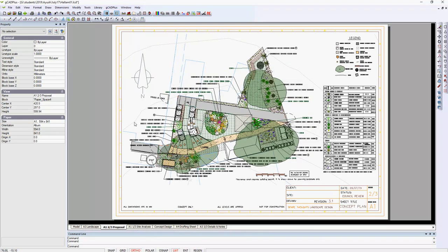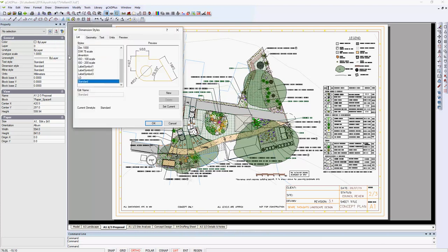Well, let's look at dimension styles. I'll click here in dimension styles, scroll up a little, and you can see there's a very large number of dimension styles associated with this drawing. There's even one called CAD block. We can probably safely delete that and scroll further down. There's one called dimension, not with an S in it. I'm not going to touch these, but they may well be in use in the drawing. But it's not good design practice to have so many different dimension styles within the drawing. We'll leave the current dimension style set at standard.